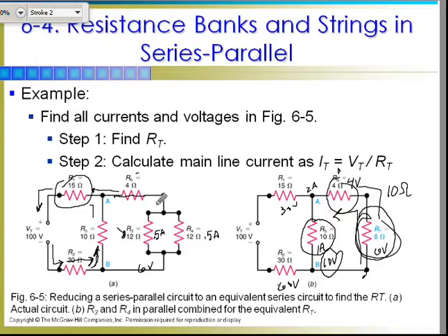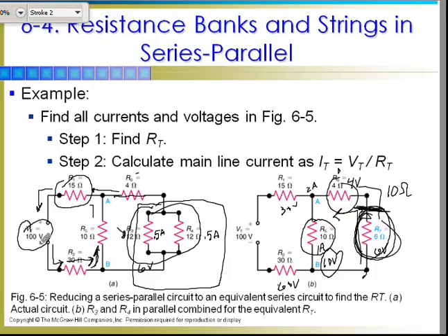So you see, the farthest out parallel circuit, to analyze that, you've got to know what the voltage drop across the equivalent resistance was in order to work in that guy. And it is the voltage drop across this equivalent resistance. It has nothing to do with the input. It's just the voltage drop across that equivalent resistance. So, simplest form, and then work your way back out.